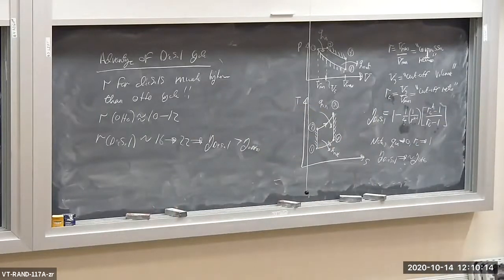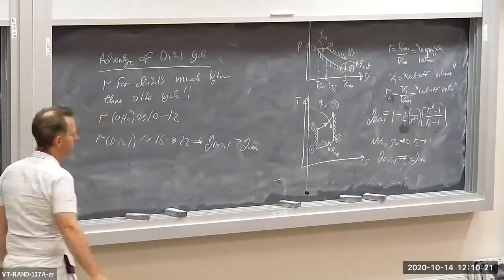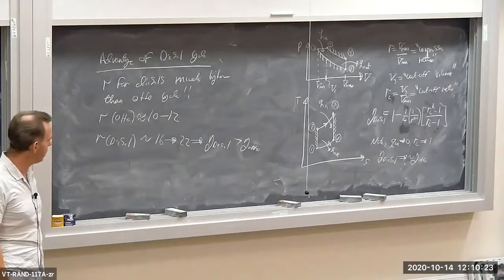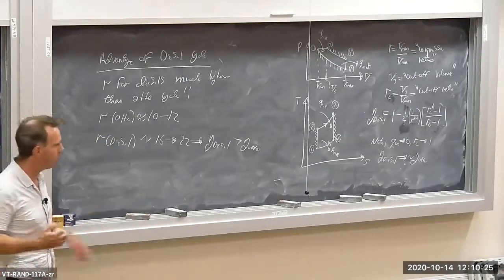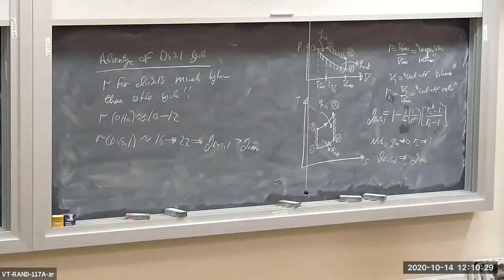You can't go too high or you start having mechanical problems. You'll end up getting very high friction. You have very high compression ratios and pressures. You have to make the engines very bulky and heavy to withstand the forces associated with those high compression ratios and high pressures.